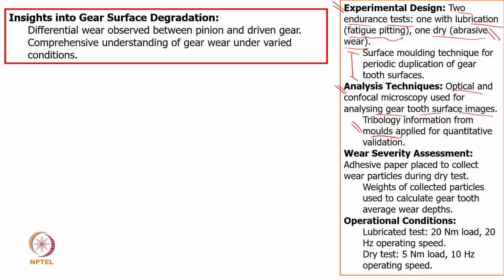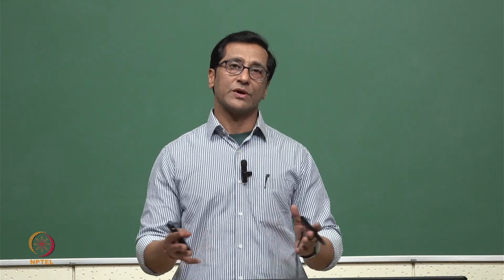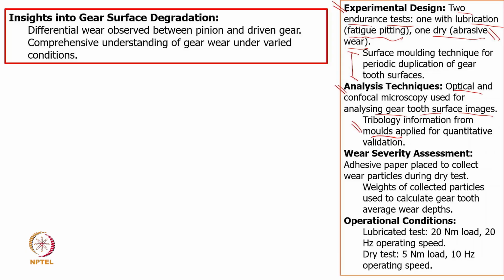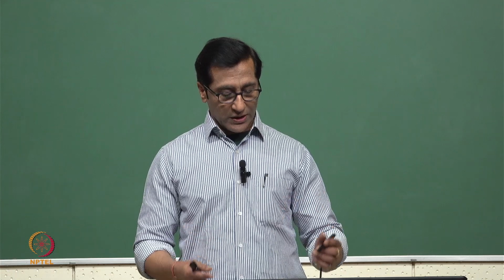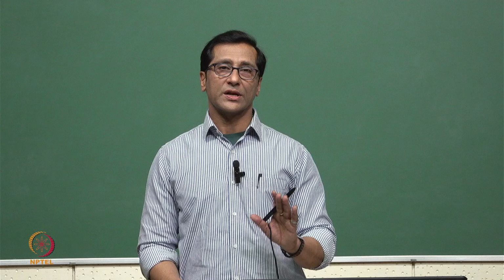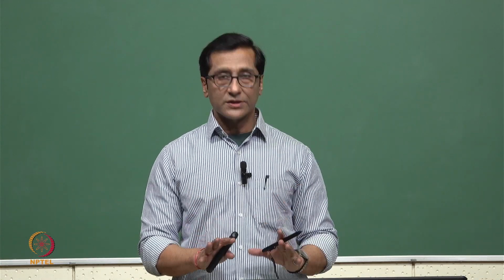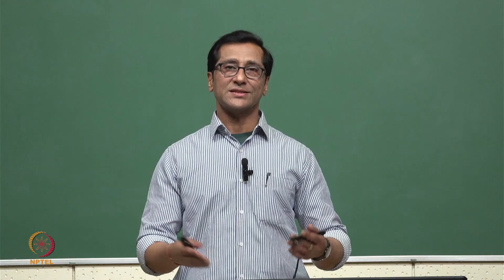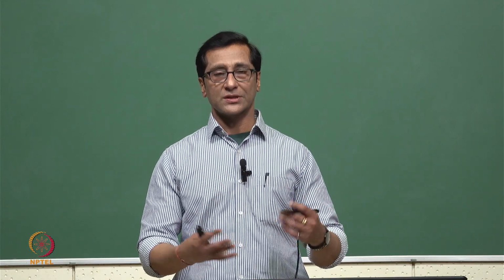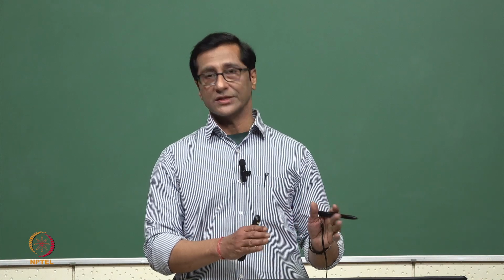So when you are trying to utilize this, you can use any technique. I prefer to go ahead with the vibration data, lubrication data, and the debris-related data. In this case, they looked at only this particular lubricated case, and they looked at only the mold-related data, figuring out what kind of pitting is happening. In an actual case, many other things are possible, but initially when you're training the system, you really require some assumptions and make a situation from that angle so the assumptions are satisfied.